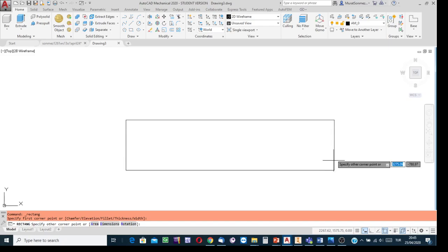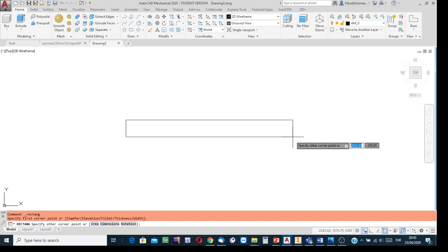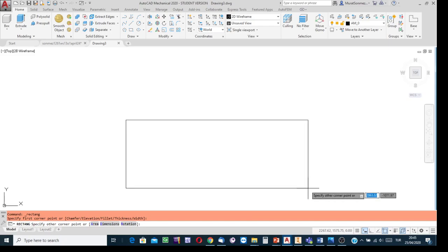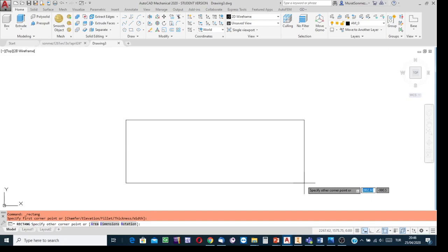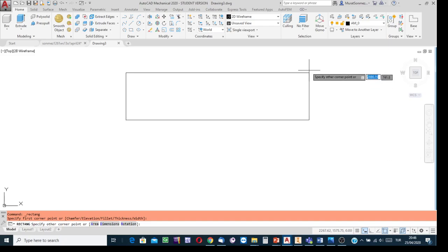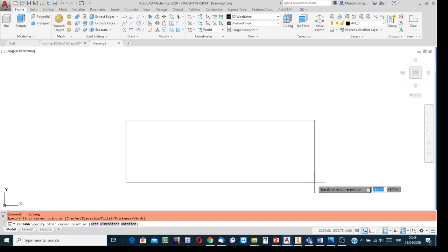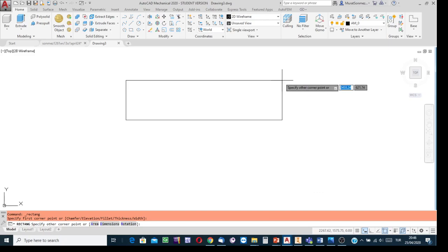But if you're going to create the rectangle, say, in this direction, extended downward, then delta y must be written negative. Yes, also from the third box, you see when I move the cursor not to a higher level but to a lower level, AutoCAD knows that the point is relative to the first one, at the negative side of the y-axis. So you see the number is a negative number. So it is important, relative to the preceding marked point, to be able to write the x and y values for the following point, for the second point.